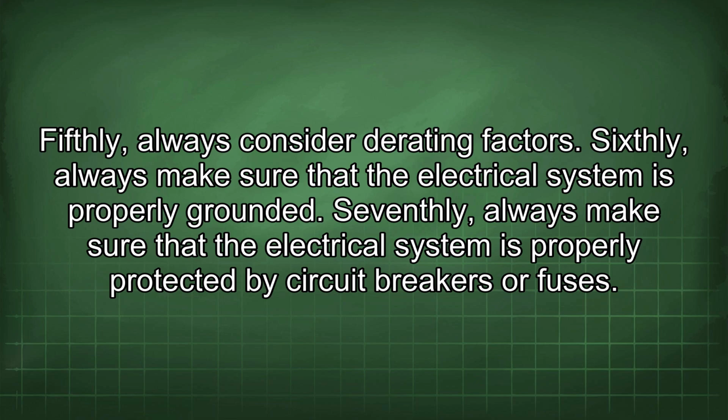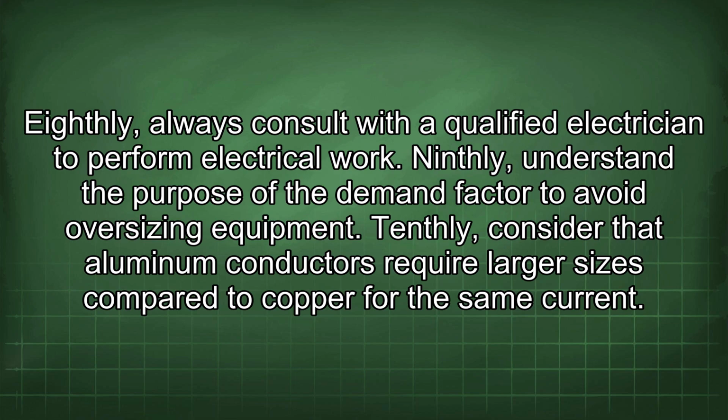Seventhly, always make sure that the electrical system is properly protected by circuit breakers or fuses. Eighthly, always consult with a qualified electrician to perform electrical work. Ninthly, understand the purpose of the demand factor to avoid oversizing equipment. Tenthly, consider that aluminum conductors require larger sizes compared to copper for the same current.